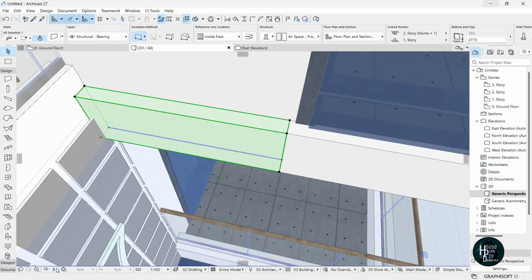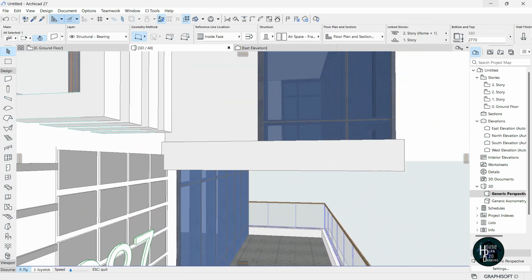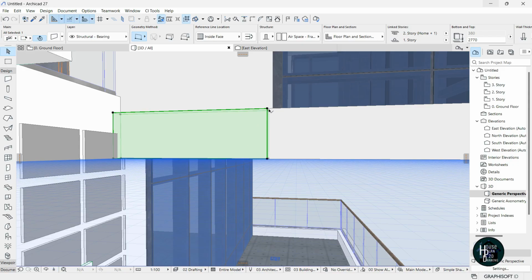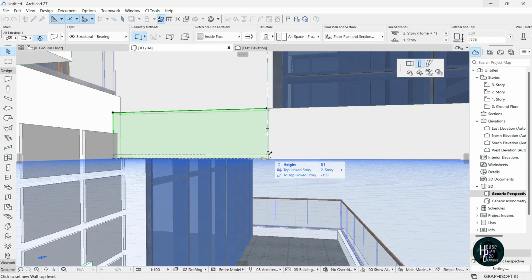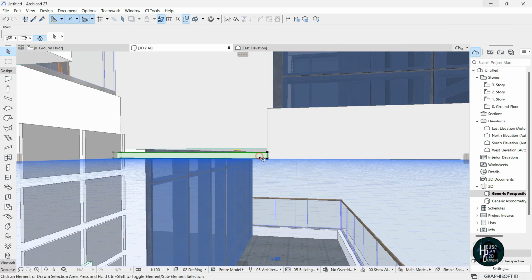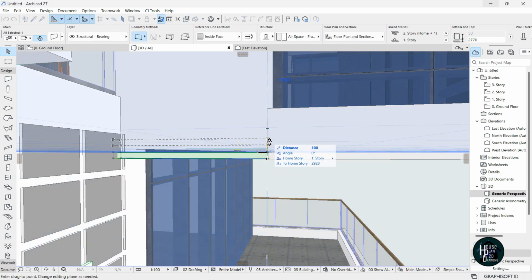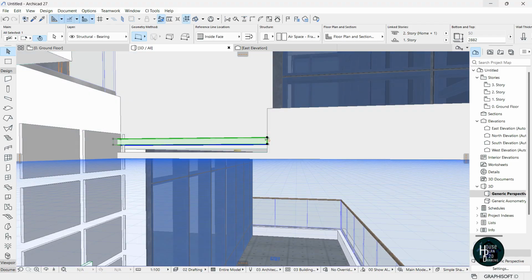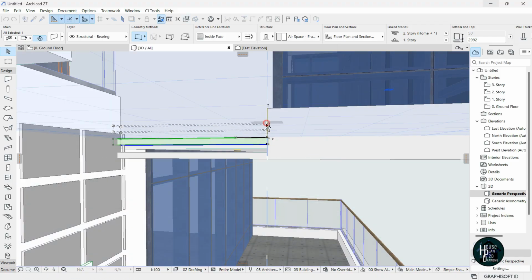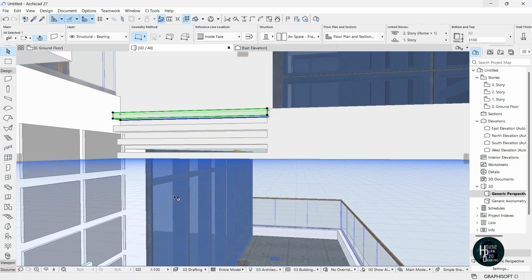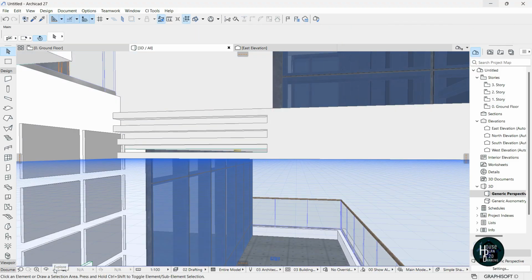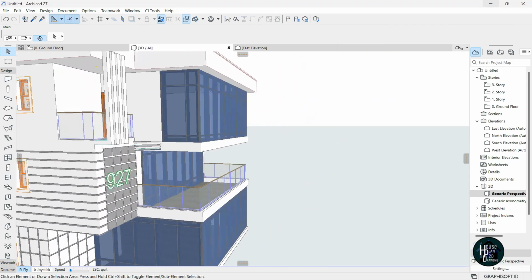Now the next thing I want us to do is to click this, make sure you're selecting this stretched height and reduce it to something around 50. Click enter. Click this, press Ctrl Shift D, make a duplicate of this one, press Ctrl Shift D again, make a duplicate of this, press Ctrl Shift D again, make a duplicate of this, and just click. Press escape on your keyboard and you should have that design come outside like so.